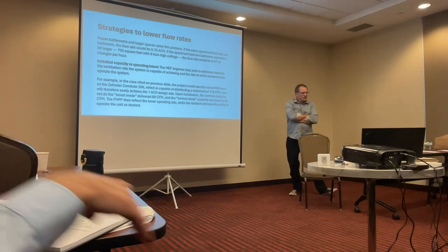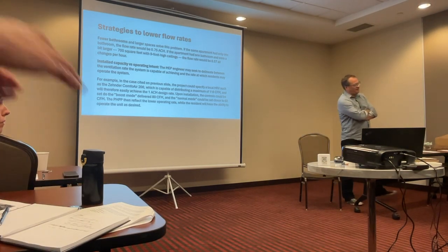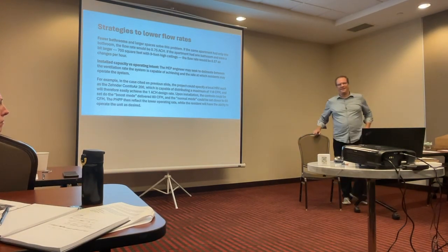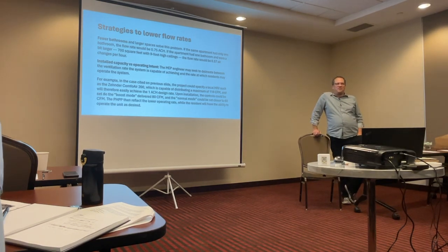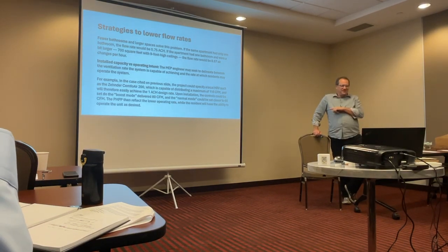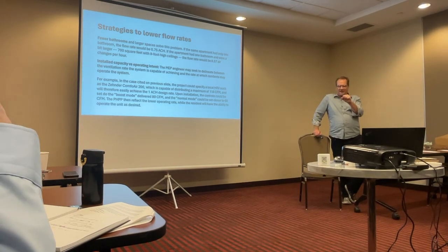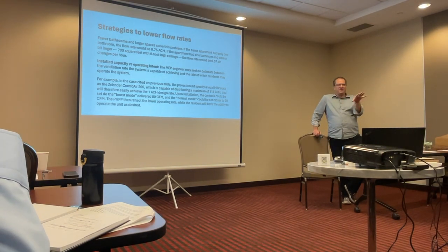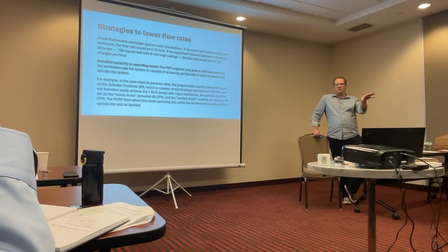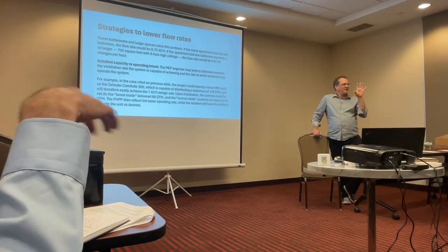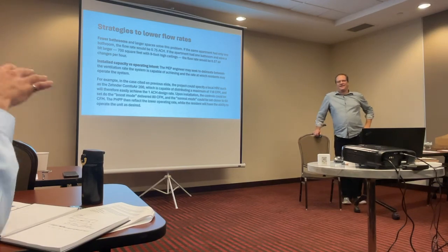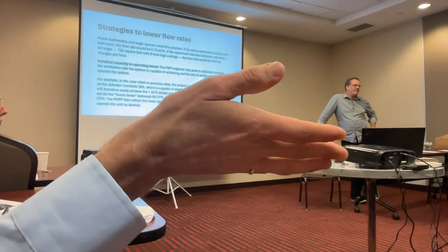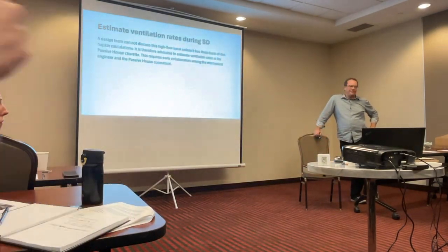But it's going to run a hell of a lot more efficiently. Yeah, and size the ERV so that it runs efficiently at that operational rate, not at the code rate. Totally agree. There's a stub of this in the draft document that's not on the slides, with a Venn diagram about this. The one thing I want to add is that you have to have your whole team know what you're doing. It can't be something that got pulled over somebody's head. Everybody has to know. It's about how much detail you go into, but it needs to be addressed. This is such a fundamental thing to the design.